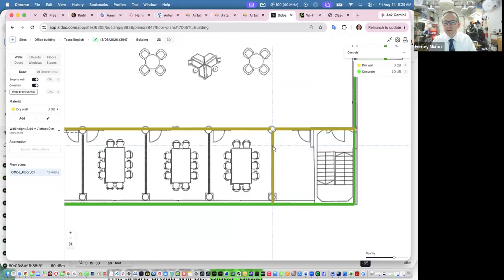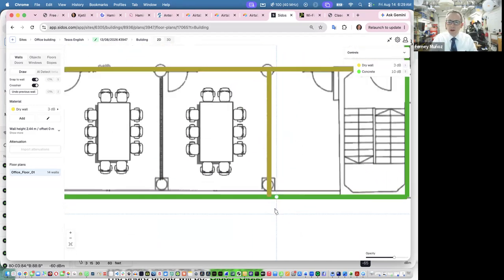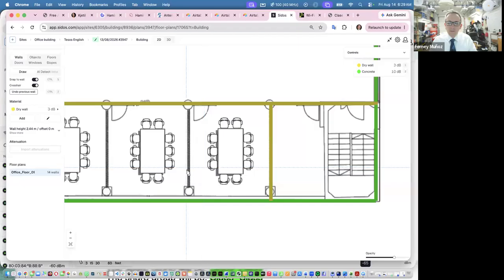See a white dot right there in the intersection? And then click. So when I right click, it just snaps to that wall right in the middle without me being too precise in clicking right where it needs to be. And that prevents me from going above or cutting it short, and adds walls snapping to other walls.